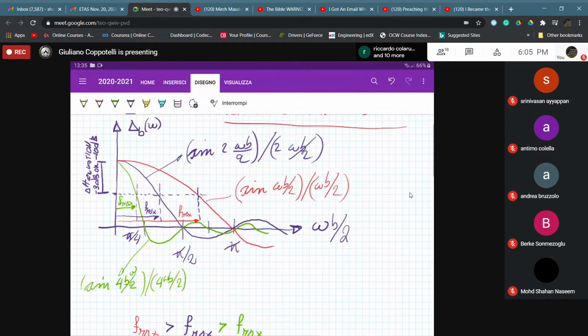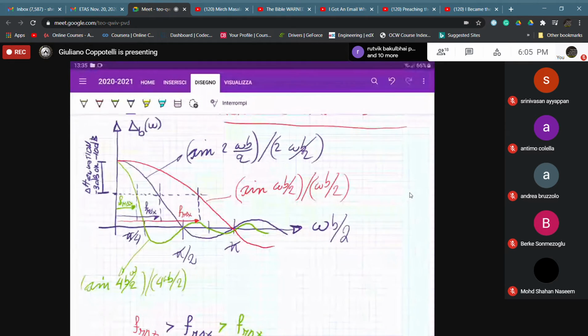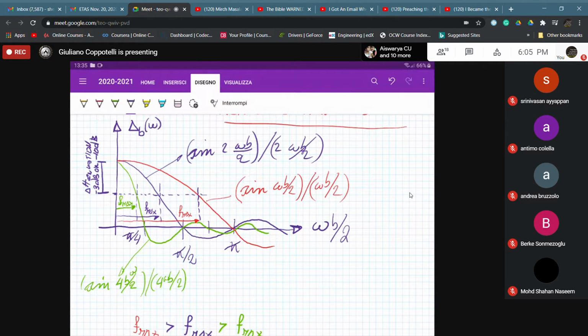On the other side, if you are willing to excite just the very low frequency modes, then you can think to excite the structure with a hammer tip that is very soft and a hammer having a very large mass, so that all the energy we introduce is acting at the very first low frequencies. That is, we are in the green behavior, just referring to this picture.